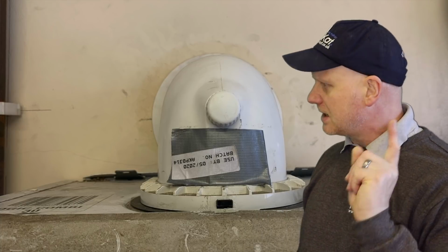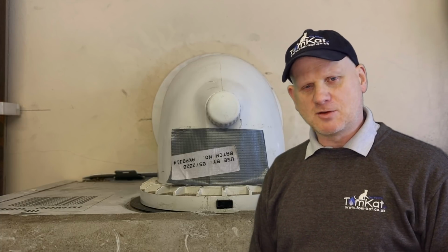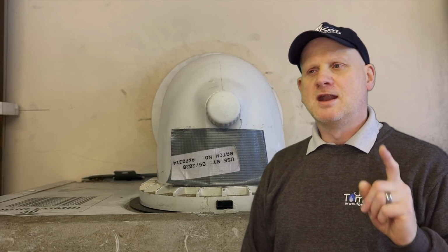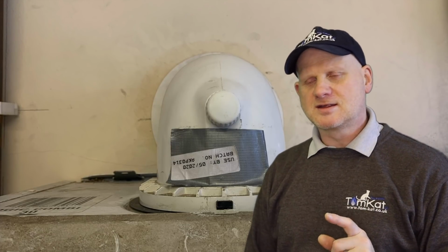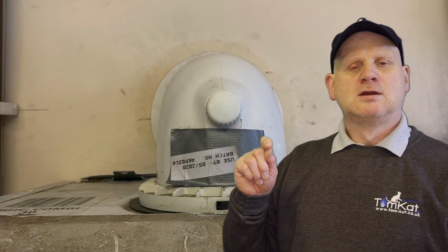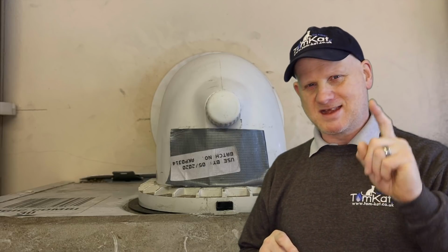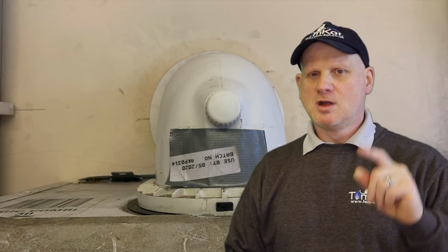So that would be classed as, in our unsafe situations, IGEM G11, at risk. Now, it also says if our products of combustion out test point is missing or broken, even without 10 parts per million CO entering the room, we will categorise that as immediately dangerous.